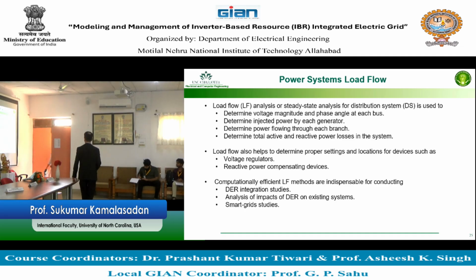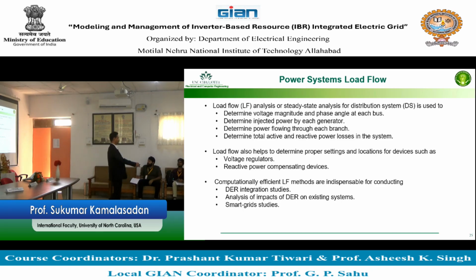Load flows are also important if you want to supply the power through renewables. If you want to connect a renewable at a specific point, what happens to the voltage at that point? Will the voltage be great if the renewable has more power coming in? If the renewable has less power coming in, will the voltage go low if the power is not proper? These things are important from the power flow standpoint when connected with renewables. So it's important to know when the renewables are connected. That is what we call DER or renewable integration studies.